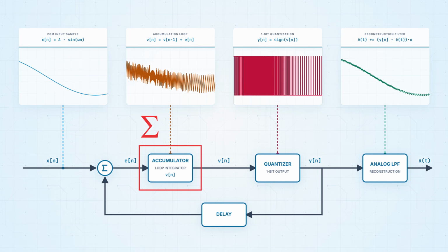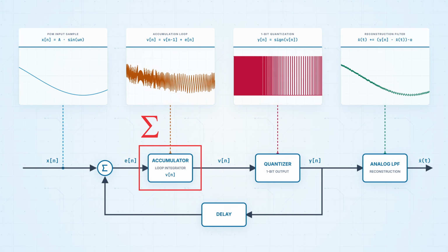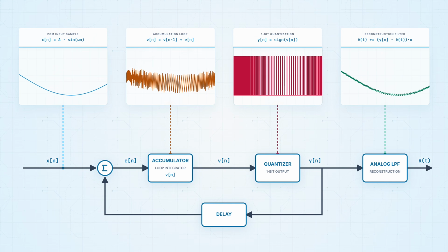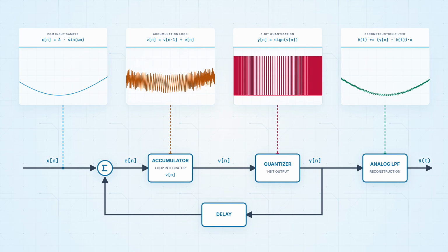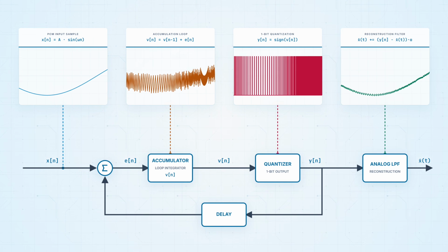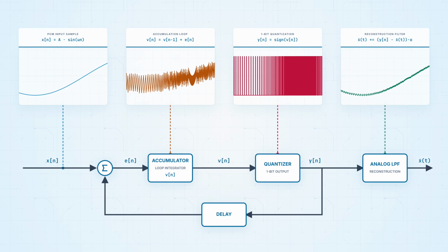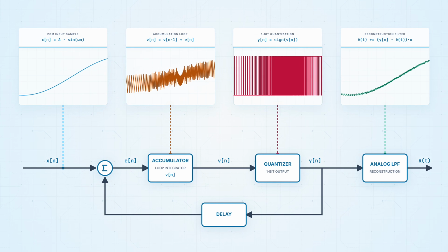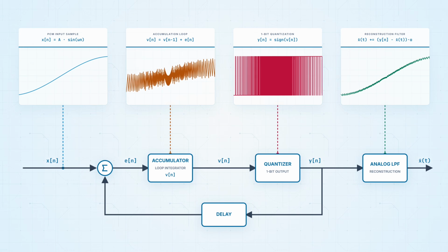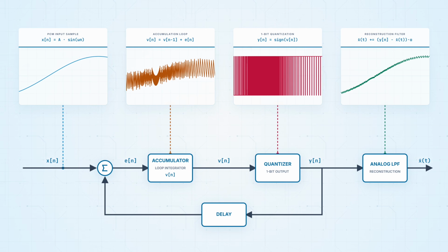Finally, based entirely on this accumulated sum, the quantizer makes a 1-bit decision to output a logic 0 or logic 1. As a result, the 1-bit output continuously toggles between its extreme digital states. However, after averaging and low-pass filtering, the average pulse density follows the input waveform.